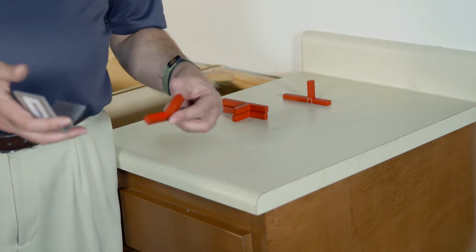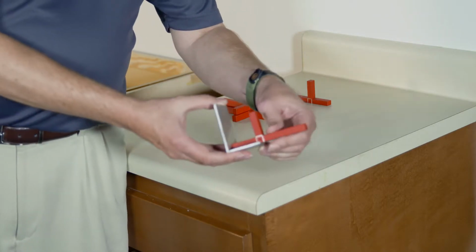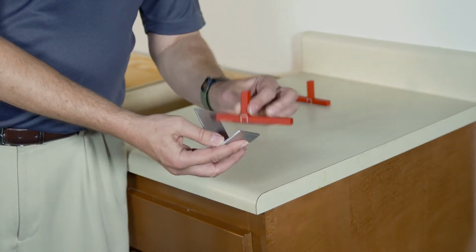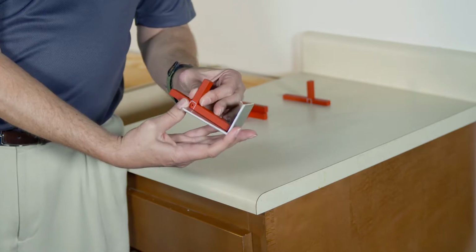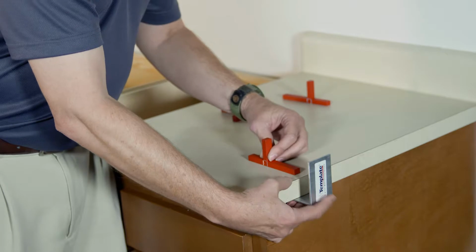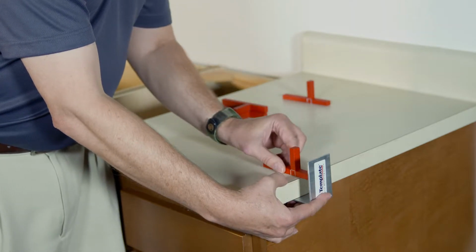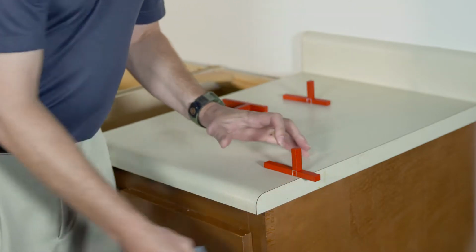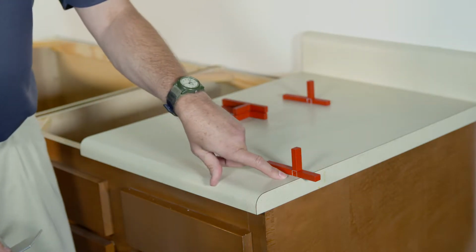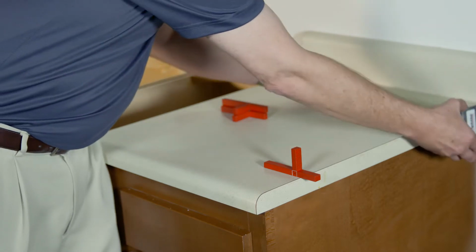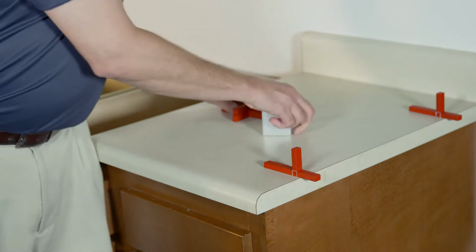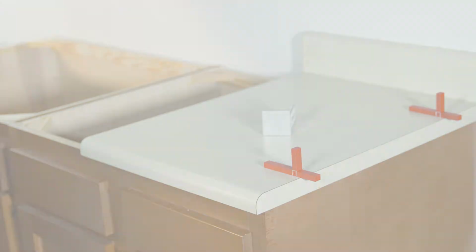So by combining with this L bracket, you can see that the short length of the T is the same as the short leg of the L, and the long leg of the T is the same as the long leg of the L. So what we do is we place the L bracket underneath the top and just snug the T bracket up against it. And now this back edge of the T is right in line with this, as well as a scribe line on the side. So I'll just do this in two positions for this edge. And we're ready to measure, and we'll just go over and work on the other side.